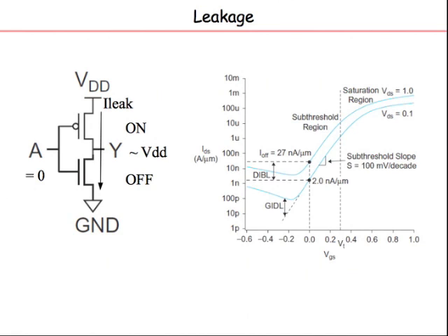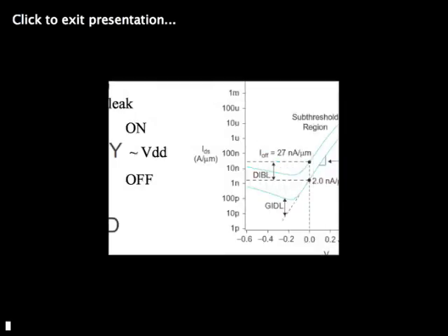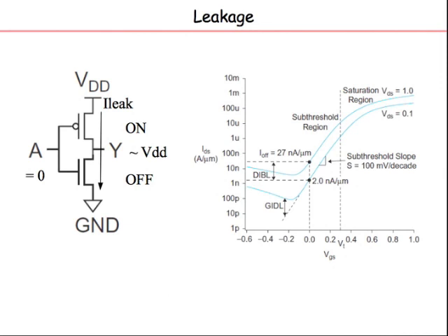Now I'm putting in a gradient. As I'm lowering the reservoir, I'm somehow also reducing the barrier. So the drain is having an impact on the barrier height. That is one of the non-idealities, called drain-induced barrier lowering. Okay, with that we come to an end for today's lecture.